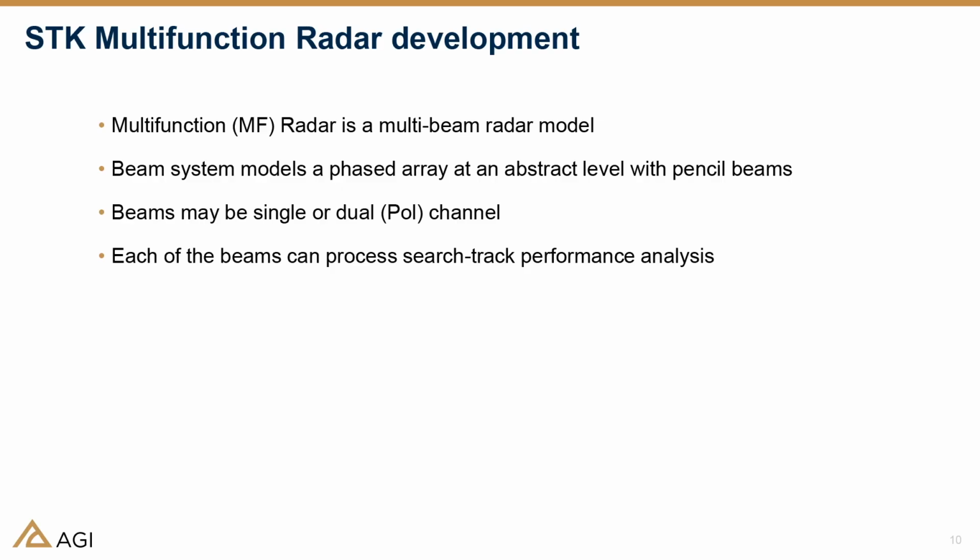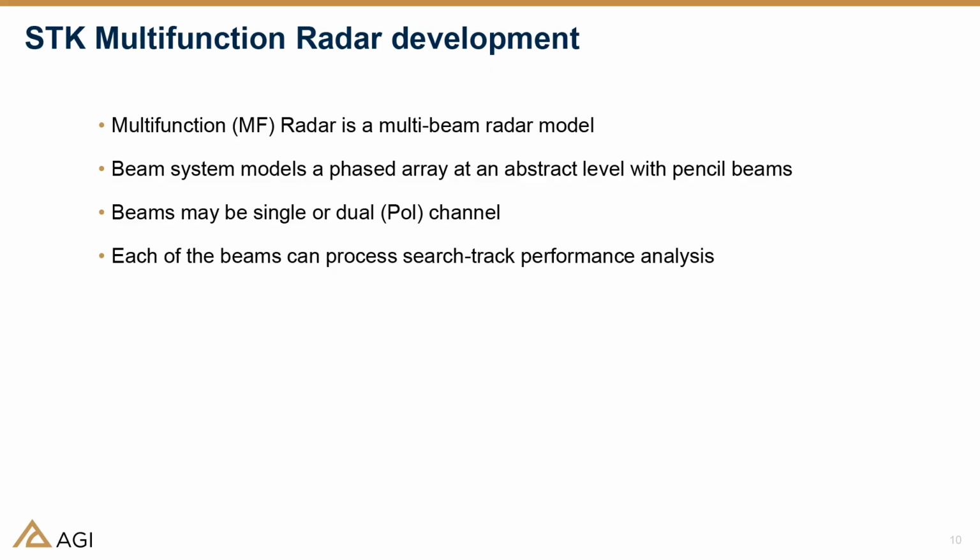Like I was saying, multifunction radar in STK is a multi-beam radar model. Currently, within the multifunction radar, each beam that you model is in the form of a pencil beam. But it's basically our way of modeling a phased array at an abstract level per beam. The beams can be single or dual channel when we were talking about the polarization, and each beam has its own independent search and track performance analyses. So what this basically means is, when you're done setting up the story that you're trying to tell with STK, with all your radars pointing in the proper direction, we can then get the data metrics out for each one of those beams independently of one another, so you can see exactly what is going on.